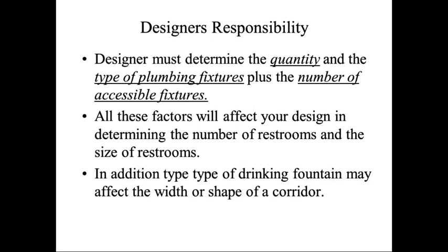Remember, back in the very first video, we have to look and see how far that restroom has to be from a particular tenant finish-out or location. So you've got to make sure that all of that is taken into consideration. In addition, you've got to look at the type of drinking fountain, which may affect the width or shape of a corridor. Remember, nothing can extend out into a corridor or hallway more than 7 inches, so sometimes they have to be recessed into those halls.